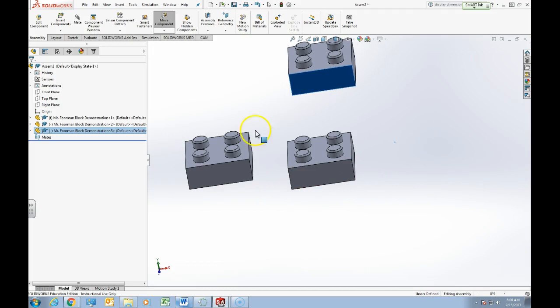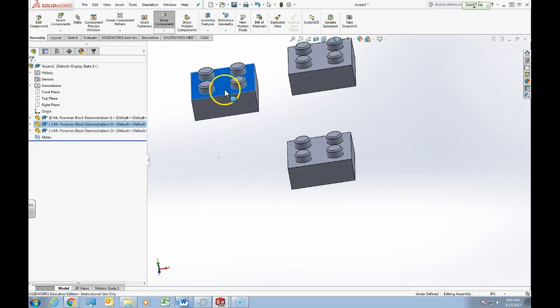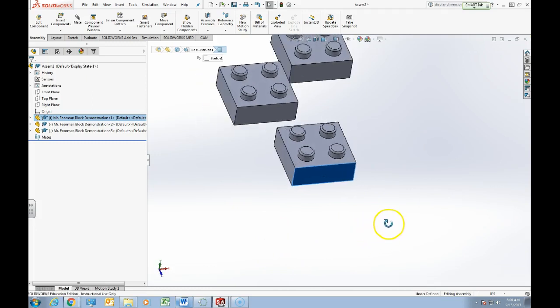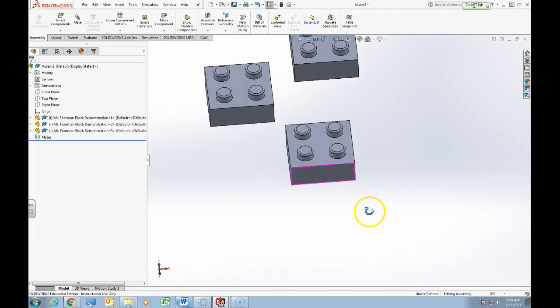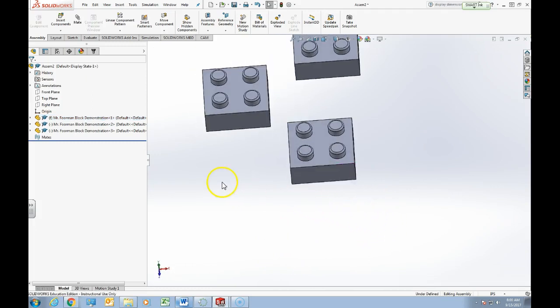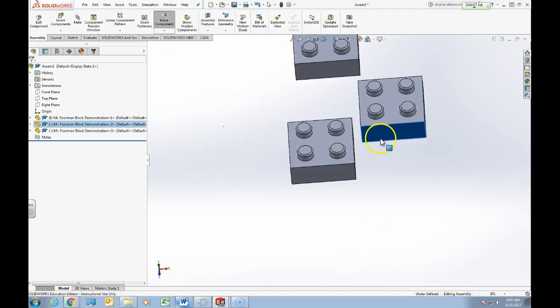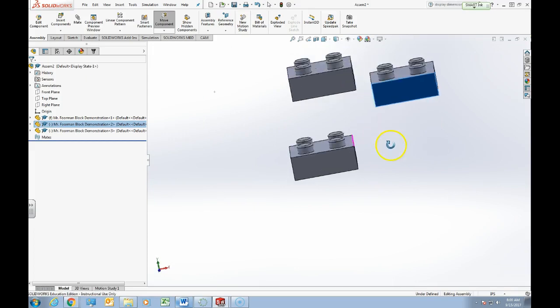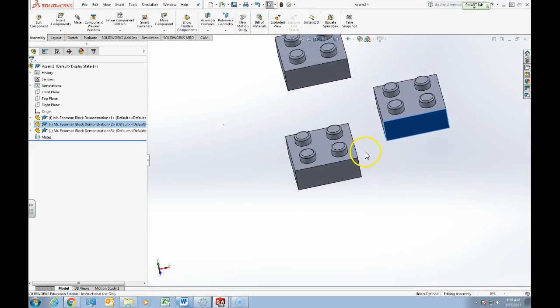Whoa, I can move that one around in space. I can move that one around in space. And this one, though, that has the letter F next to it, is what is called fixed in space. It says the selected component is fixed, it cannot be moved. So that is stuck in space right now. But wait a minute, we want to make this one sit next to that one as if it was on the table in front of you, butted up against that.